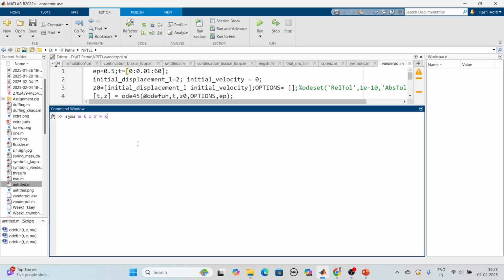Okay, these will be written like this. However, my x will be written like this, x(t). See, by default, t is taken as a variable for time. So if I define my x like this, x in brackets t, this means that I'm telling the symbolic toolbox that okay, you define x as a function of t, where t is my time. Now I'll press enter.